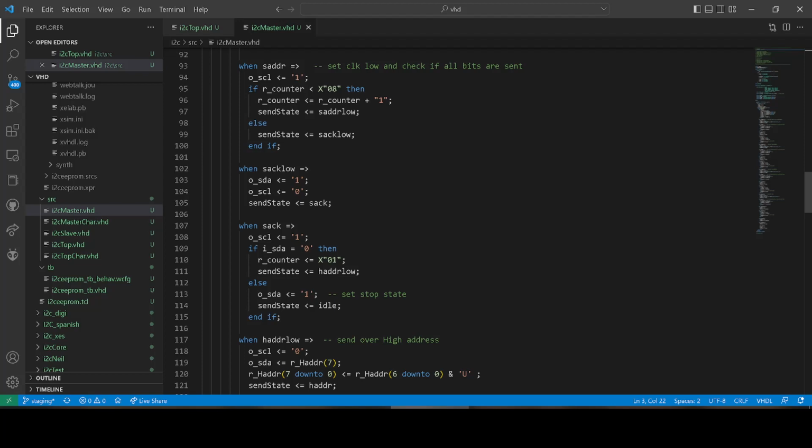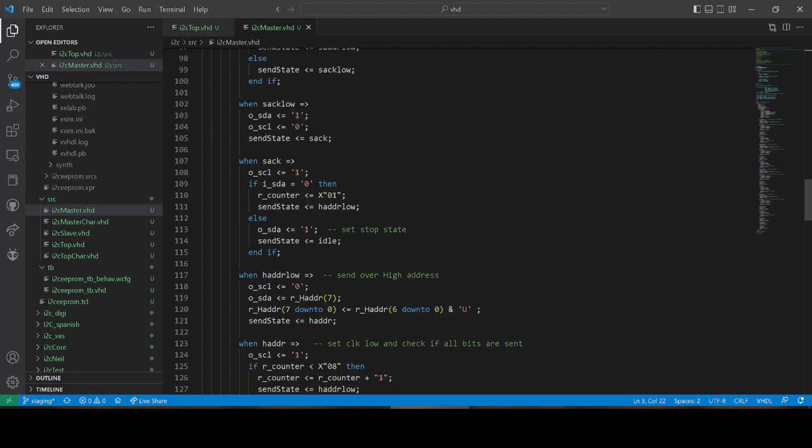In this case, I had to put the data in a high state that lets the tri-state buffer know to put the data in what's called a high impedance state, and therefore allows the actual slave device to send data back over the same wire. So we did this. We're doing this on the low clock. Now on the high clock, we're basically waiting for the data.